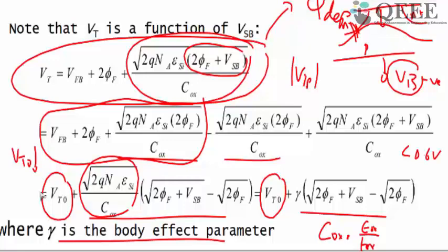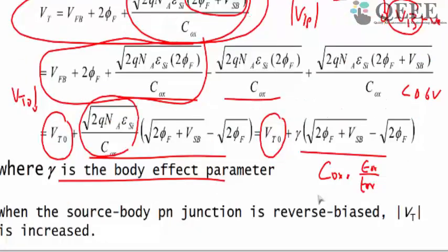There are some circuit design companies which utilize this principle. You apply something known as an adaptive body bias. You apply a small forward bias so that you can speed up the transistor. Similarly, you can apply a negative bias, that is, you increase the VT of the transistor, which allows them to reduce the off current. So, that is all about intentionally applying a substrate bias.